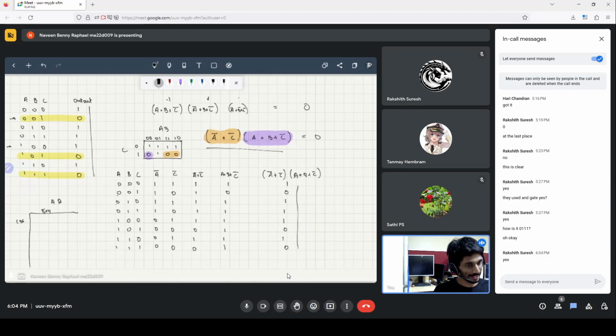In that big rectangle, you fill in all the zeros and ones, and you select all square regions. But you must make sure the square regions have a dimension that is a power of 2. Once you do that, you can easily identify the sums or the products, and there you go. You have simplified this arbitrary output into sums of products and things of that form.